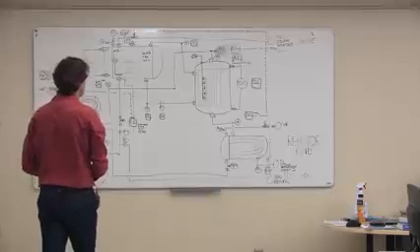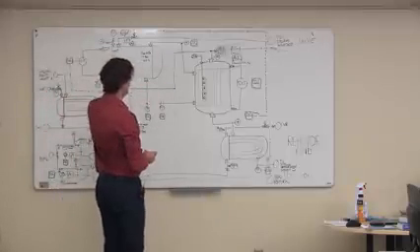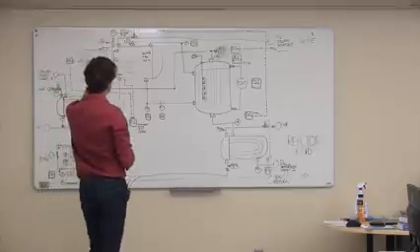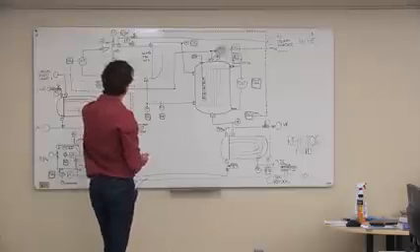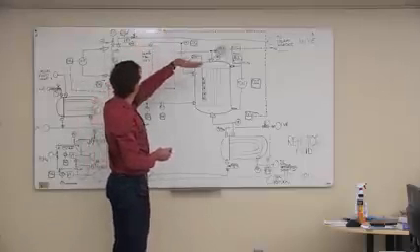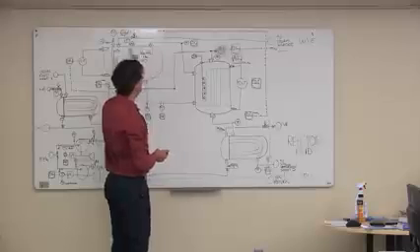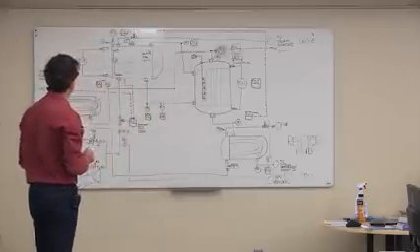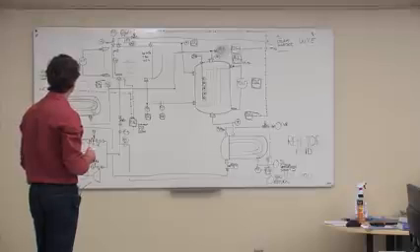So we know what the steam flow rate is going into the header. That's a pretty common thing to want to know. We're not going to try and control the steam header pressure. We're just going to basically put steam into that header, and the header has to deal with that pressure or else get rid of the steam somehow.